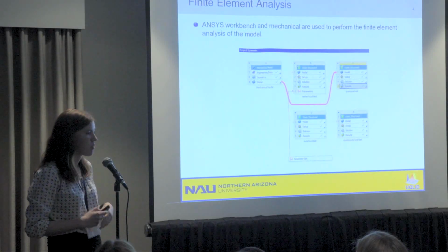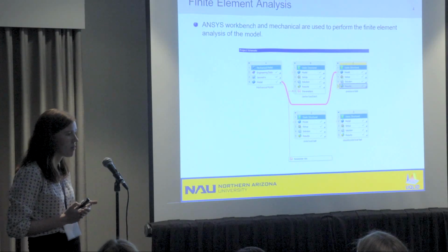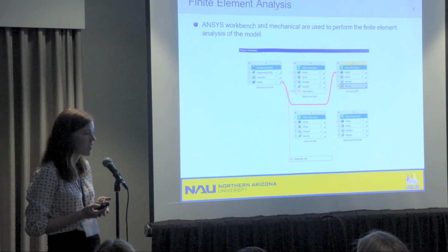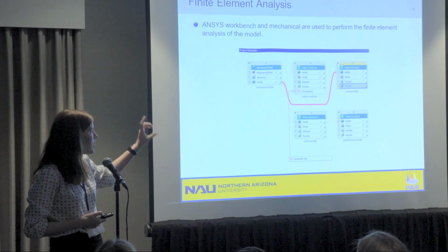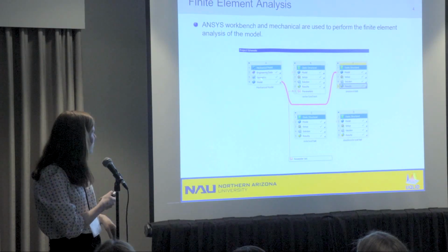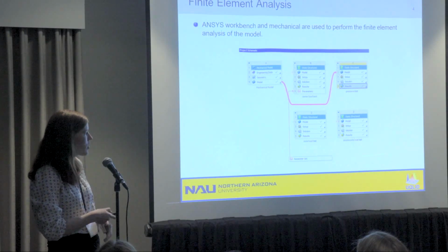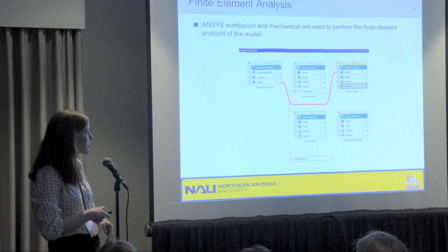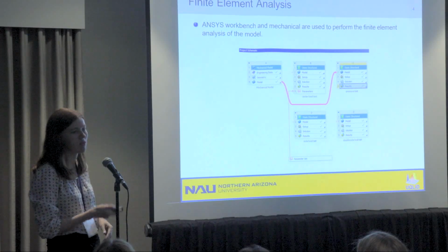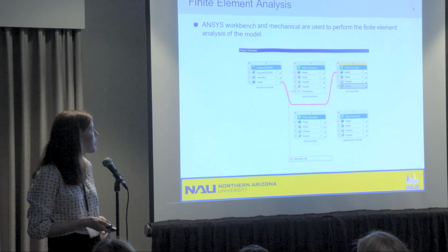So once that was done, I was able to move on to the actual finite element analysis. I used ANSYS Workbench and ANSYS Mechanical together to get this done. Here you can see a snippet of my ANSYS Workbench with square A having all the setup of the problem, and then these other sections basically have the different loading conditions, so that makes it really easy to add different loads and different perturbations of materials.